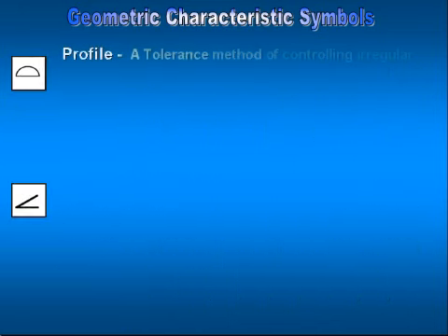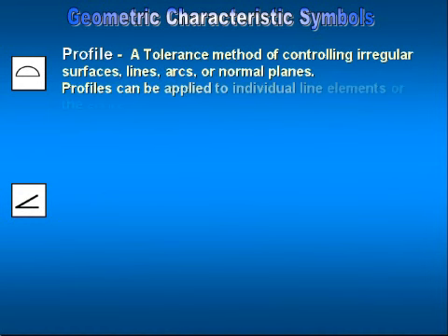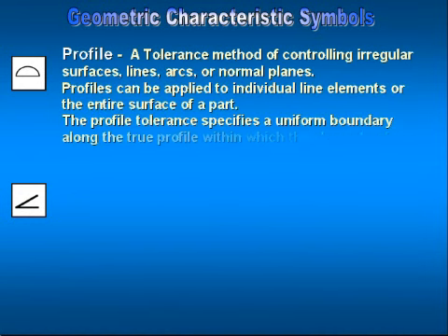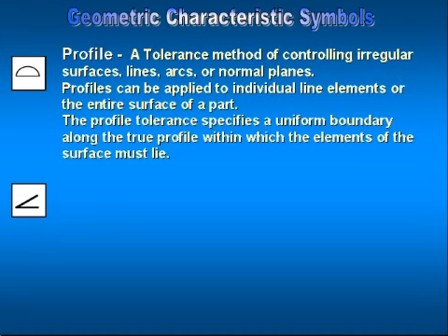Profile. A tolerance method of controlling irregular surfaces, lines, arcs, or normal planes. Profiles can be applied to individual line elements or the entire surface of a part. The profile tolerance specifies a uniform boundary along the true profile within which the elements of the surface must lie.